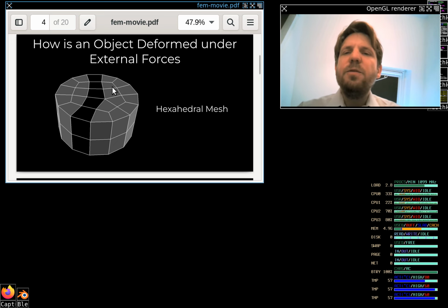And then what you want to do is apply forces on this object and see, for instance, how this object deforms, what stresses these little elements are going through, and what this actually means. This way you can make your static mechanical calculation. So you anchor some points, you put some forces on the others, and you see how the object deforms. You can imagine that you can build bridges out of this, and airplanes and whatnot, and apply forces on wings or on the bridge as you imagine cars going over it, and see how the object reacts to these external forces.